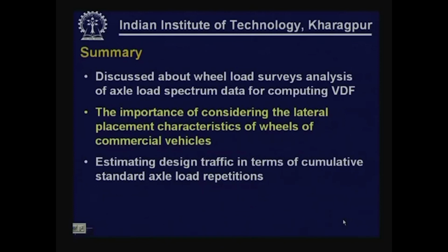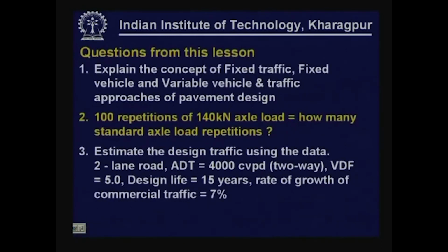We also discussed about axle load surveys or wheel load surveys that can be conducted, and also about the importance of considering lateral placement characteristics of wheel loads of commercial vehicles, and we have seen how using all this information equivalent number of standard axle loads can be estimated for a design life period. Let us see some questions that we would like to be answered. We will provide the answers for this in the next class.